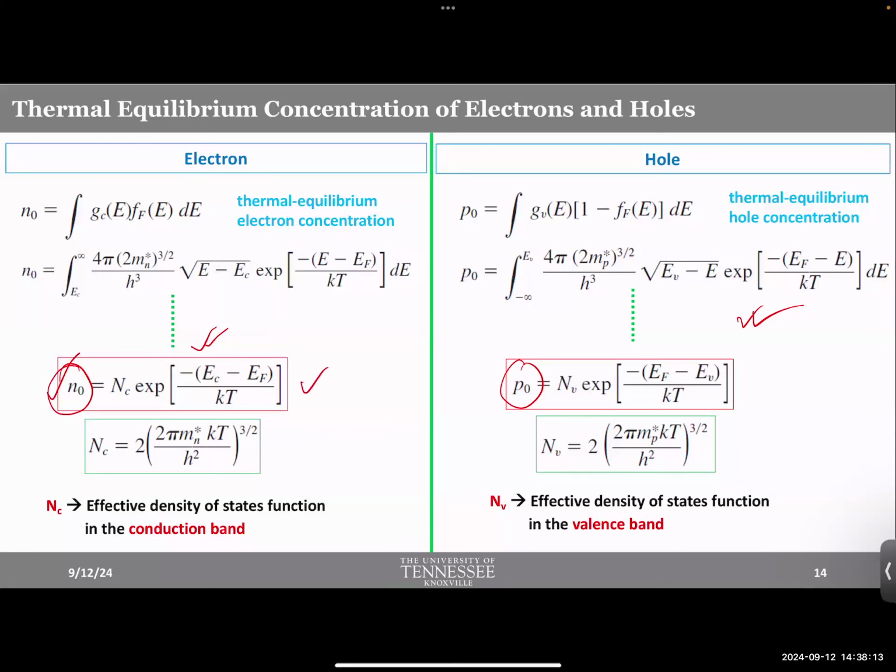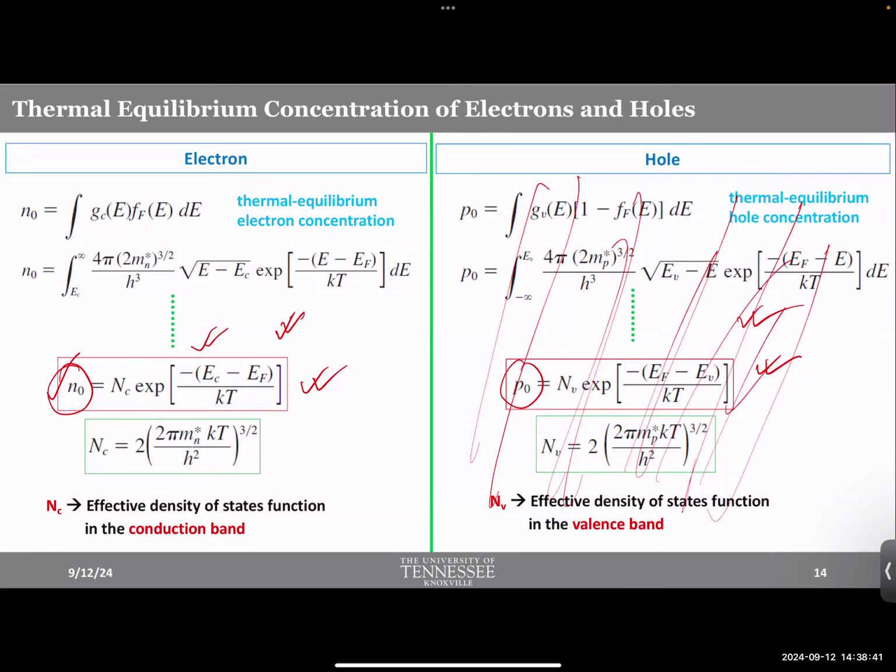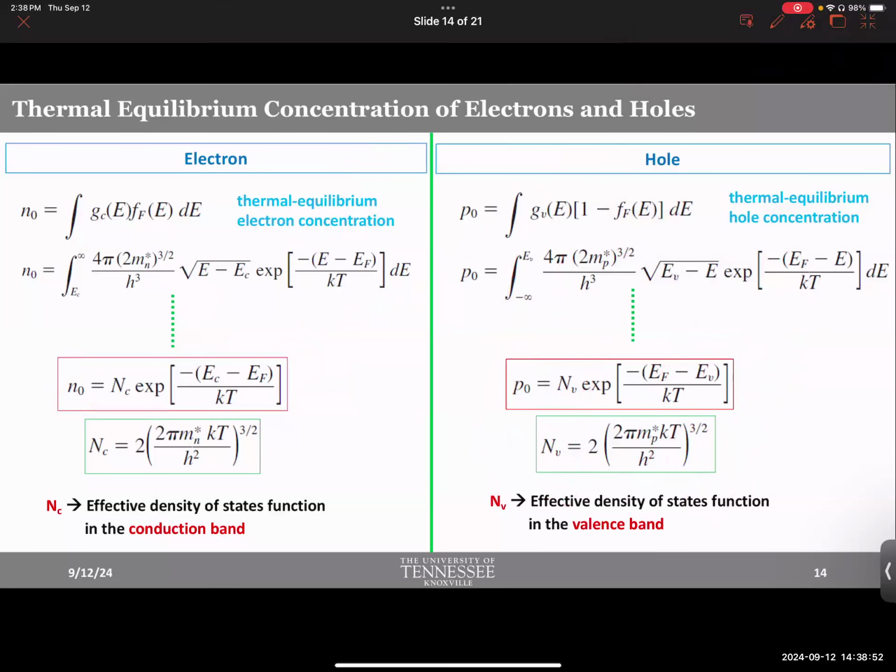And we noticed the symmetry between these two equations. And that's something that will keep coming back over and over again as you study semiconductors, more or less. There will be two kinds of doped semiconductors that we typically use. We will be typically using N-type semiconductor and P-type semiconductor. And it turns out whatever you do for N-type will often be symmetric or somewhat similar for the P-type. So that simplifies our job. So even if you don't pay attention primarily to one kind and just focus on the electron part, you could ideally, for most cases, just portray that in terms of holes and get similar equations out of it. And you keep seeing that over and over again.